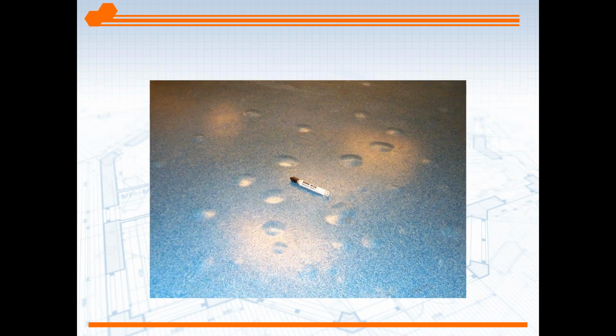Here we're looking at an epoxy coating that has, I'll call it, a decorative flake embedded into the surface. Most people think that epoxies have a very tenacious bond, and indeed they do. But some epoxies, if they're not formulated for exposure to excessive moisture or to alkaline salts, can fail.